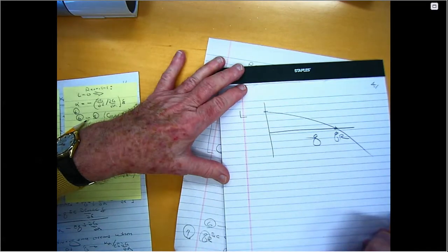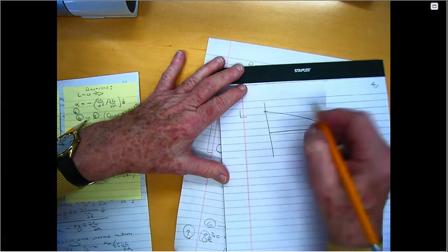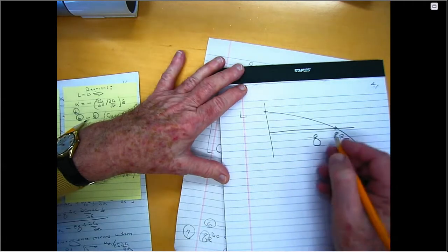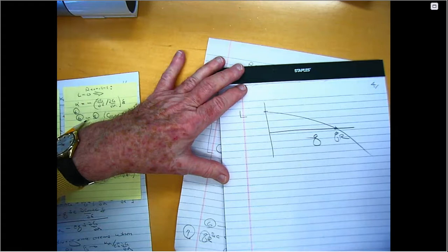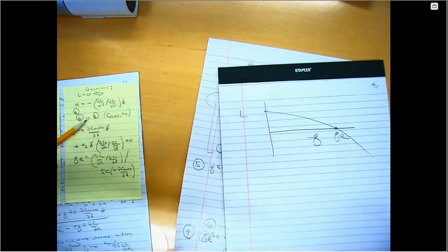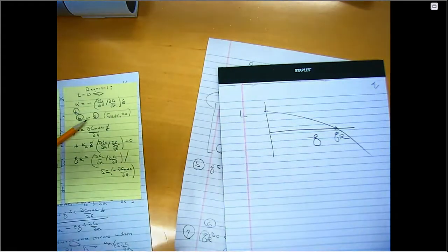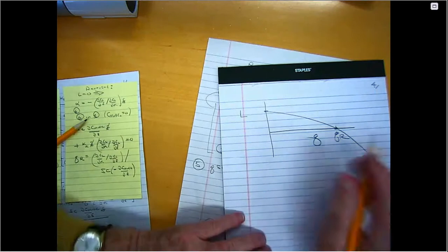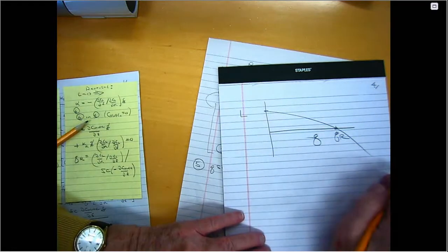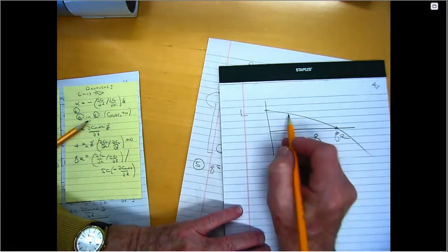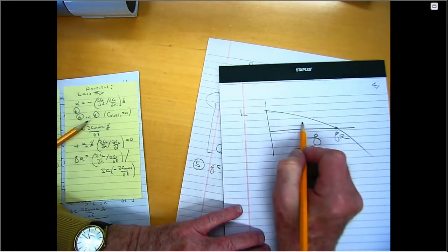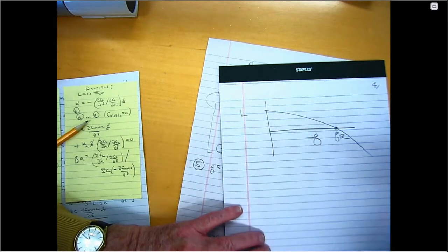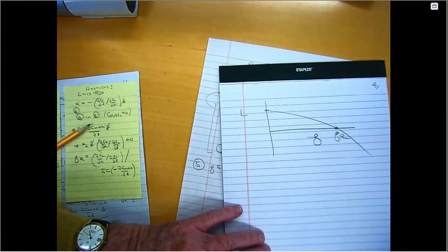And sometimes that whole curve is interesting, because people, rather than looking at reversal, you don't usually want to fly the airplane above reversal. Sometimes you do, if you have multiple control surfaces, and each one has their own reversal Q and you do it properly. But for a single control surface, you wouldn't want to fly above reversal. But even at lower values, you might lose enough lift effectiveness. The lift might decrease enough due to aeroelasticity that it would not be a good thing.